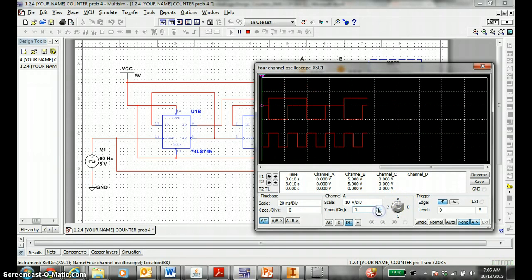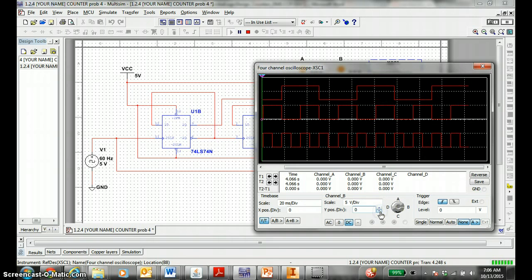separate it from the center signal. So we'll raise it up 2 volts. Go to channel B here. I guess we could make everything 5 volts per division. Might be better. And let's squeeze it in there. Channel B, let's go 5 volts per division. Let's keep it at the 0 level. We're not going to make it higher or lower so we could see it.